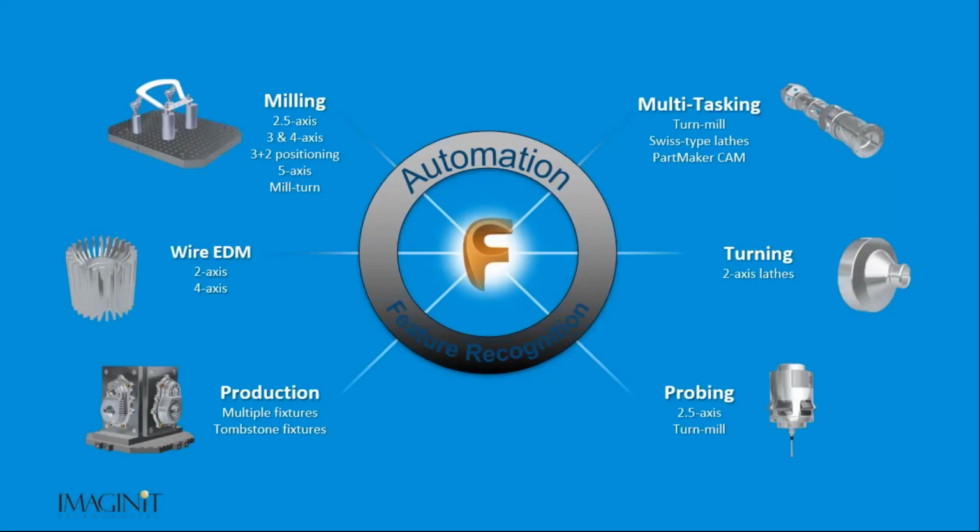So what does FeatureCAM support? Like I said, it supports a variety of different machines. We'll start here with milling, going from 2.5 axis, 3 axis, 4 axis, 3+1, 3+2 positioning, 5 axis, and all the way up to mill turn. It supports multitasking like Swiss type lathes, part maker and turn mill, and basic turning for just 2-axis lathes. It has a great feature for probing that works in conjunction with milling in any one of these different machines.